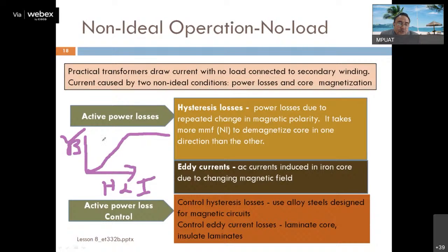So this is the linear portion, this is the linear portion, okay. And then at a particular limit called the knee point, this point is called the knee point. Beyond this, if you increase the current, the magnetic field remains constant. Okay, now this curve has come.